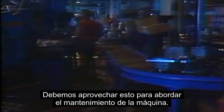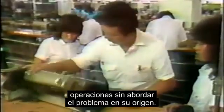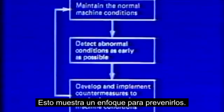We need to take advantage of this to address machine maintenance at the source, rather than by collecting the information after the fact. To facilitate this communication at Toyota Auto Body of California, a visual aid was installed to inform maintenance crews about the condition of the machine. So they called this a maintenance Kanban. Just as inspecting parts after the defects are produced can never totally eliminate defects, we cannot establish trouble-free operations without addressing the issue at the source. This shows an approach to preventing them.